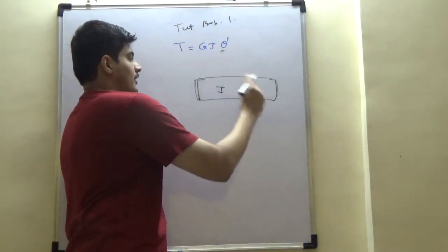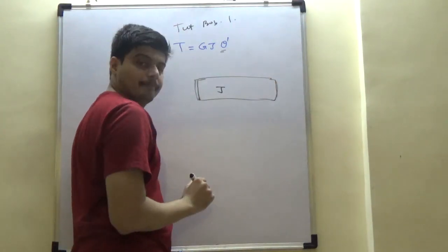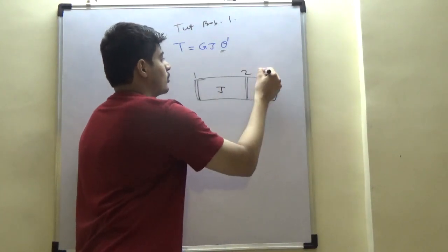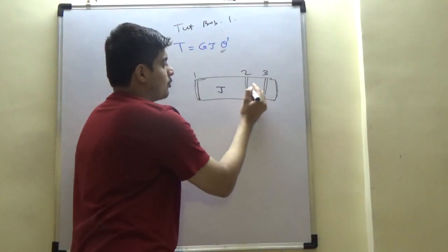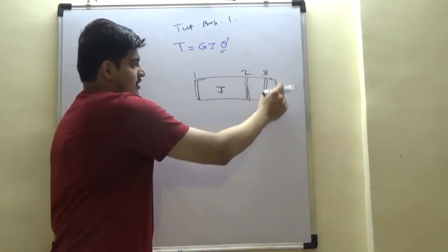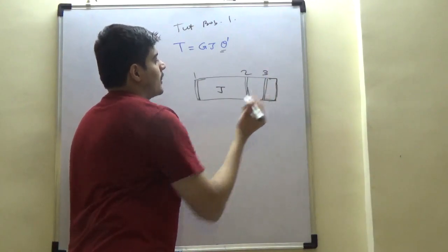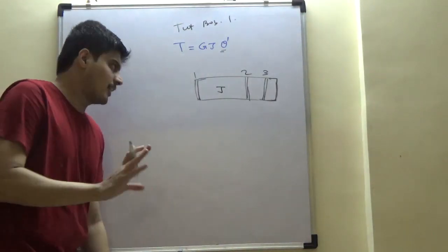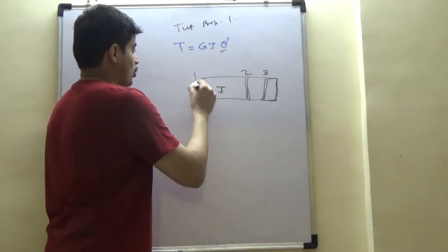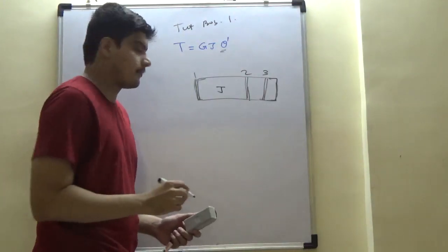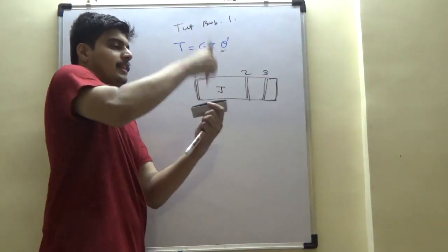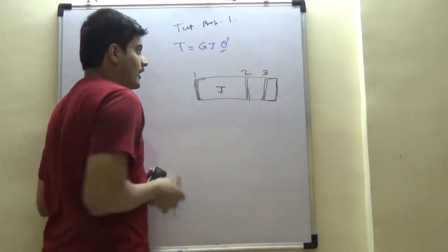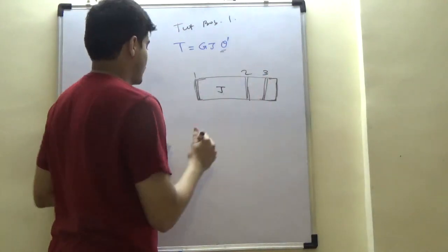There is going to be torque as we discussed, right? These are the different wing sections. I am going to call them 1, 2, 3 just for convenience. Some next to the middle, almost towards the end, right? Extreme edges we will ignore because, as we said by St. Venant's principle, some of these end effects of stress are local, so we will ignore. This is the root chord, which is attached to the fuselage. This is getting distributed with lift, right? And its twisting moment, which means the torque generated by aerodynamics, is going to twist this wing.